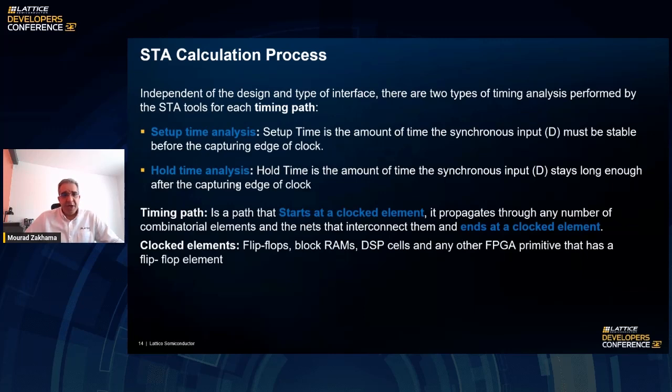When we talk about a clocked element, it's not only the flip-flop. It could be a blockram, because the blockram output will have some flip-flops to clock the data out. Also, it could be DSPs, any other primitive that has a flip-flop element in it will be analyzed. That's the job of the STA tool, making sure that any synchronous logic that you have in your design is checked for the setup time and hold time analysis.